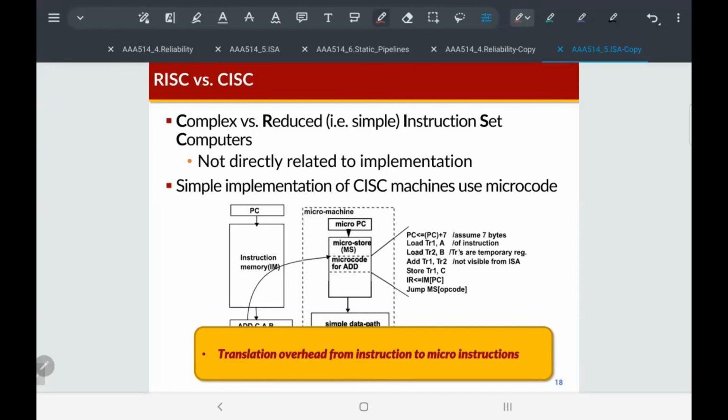The main features of the RISC type ISA: the first feature is that data in the main memory are handled only by data transfer instructions like load and store instructions. Another feature is that the instruction length is usually fixed, like 32-bit for ARM or RISC-V.